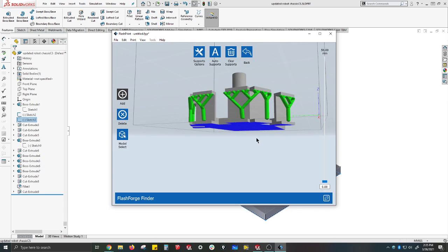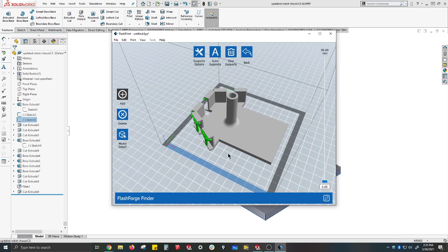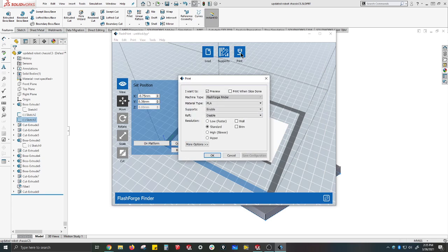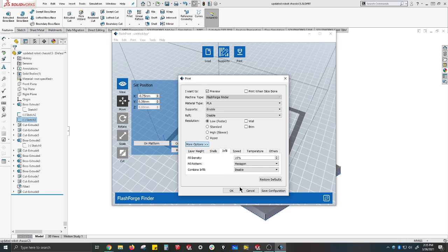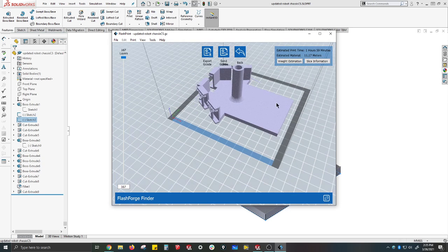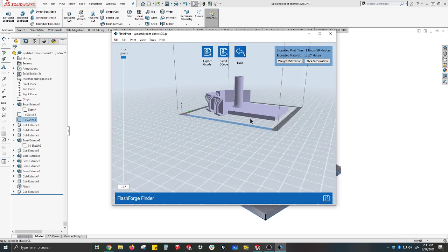And I don't know if these are the right dimensions, by the way. I haven't checked this or anything. I'm just using your part. But let's just see what we got. I'll go to the slow speed, the faster speed, which means I've got an infill at 10%. I'm not going to add a brim. Yeah, we're at 2 hours, so that's way better than 9.